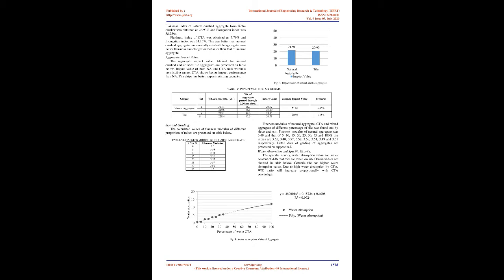The tests performed are as follows. Fineness test. The fineness of cement is calculated by sieve analysis method, dry sieving method. Fineness is checked for the quality of the cement material. Fineness of cement is responsible for the hydration and hence the rate of gain of strength and also the rate of evolution of heat. If the cement is fine, then greater is its cohesiveness, which is the property required in the concrete because it gives compaction to the concrete.